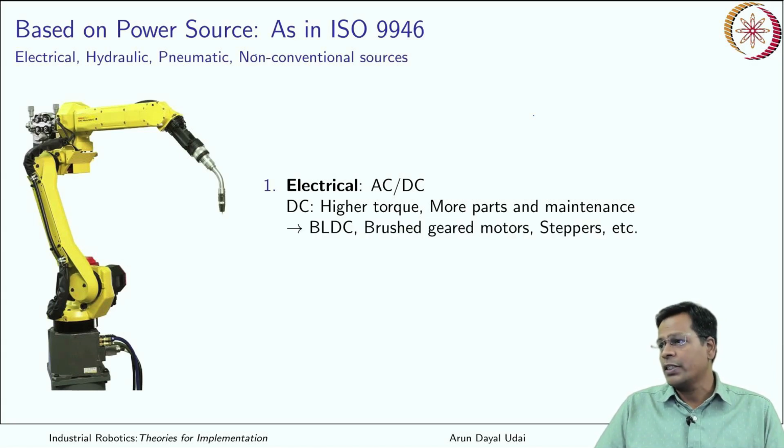A BLDC motor, that is a brushless DC motor, is lighter. It bears almost similar features to a standard DC motor. However, the drivers are a little bit complicated. It doesn't have brushes or a commutator, which makes it even more compact. Because it has fewer parts, no wearing off of brushes can occur. It has more life as well.